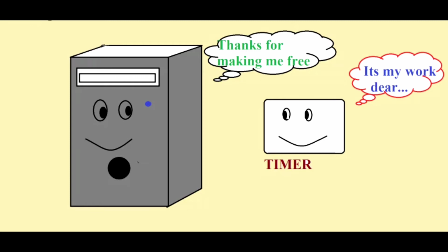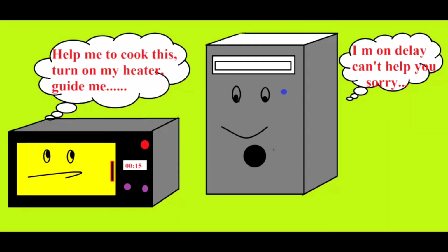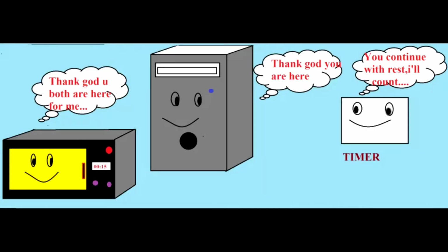And after 30 seconds, when we open the door, we get the same output as we gave the microwave as input. Because for a software delay, we have to apply a loop, so when we press start, our processor goes into a delay for 30 seconds and doesn't perform its other tasks, to turn the heaters on, maintain the temperature, display the time, rotate the dish, etc. So the timer is also a very important part of this structure, as it performs the task of maintaining delay, and the processor is free to perform the rest of the tasks.